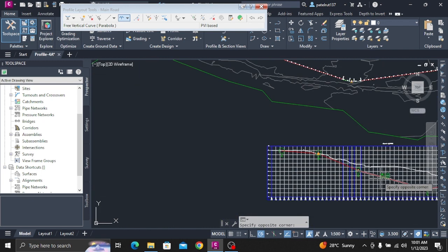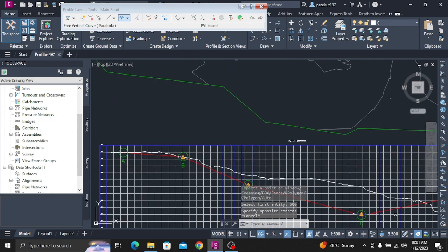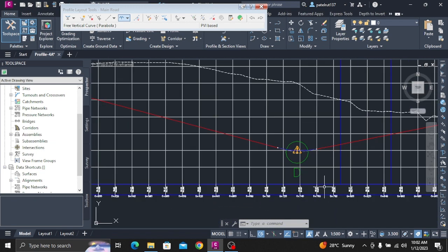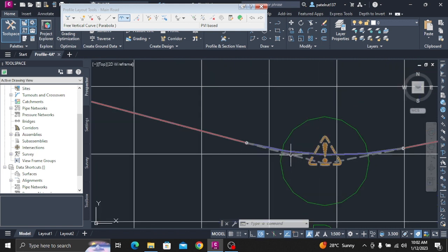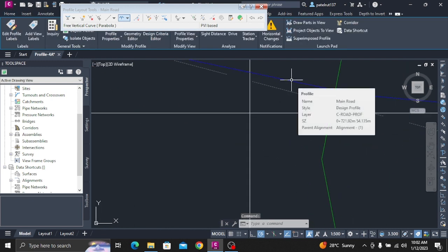On the Pipe Network display page, in the Select Stacked view to specify options for list, select Bottom view. Most of the pipe network is on the right-hand side of the alignment. You will specify that the pipe network components will be displayed in the profile view that displays the right EOP profiles. In the Select Pipe Networks to Draw in Profile View area, select the Select checkbox. In the Name column, expand the network, 1, Pipe Network.